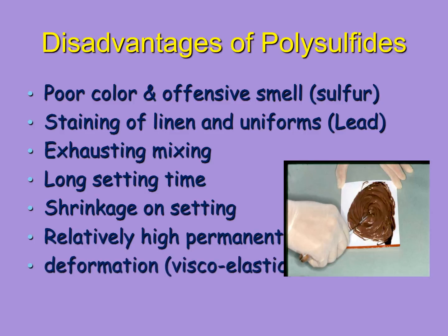The disadvantages of polysulfide are the poor color and offensive smell because of the sulfur, the staining because of the lead, and exhausting mixing, long setting time, shrinkage on setting, and relatively high permanent deformation.